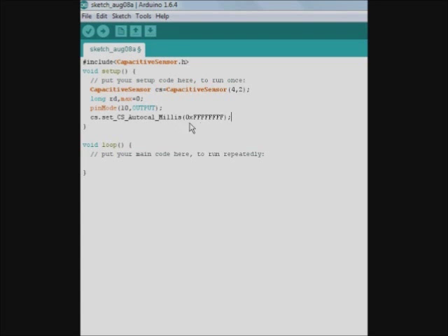What 0xFFFFFFFF does is it turns this recalibration off. So we'll just calibrate our Arduino once, and that calibration will carry on for the rest of our game, so that it doesn't create a problem for us. You can experiment with this and discover what it means if we change this or if we don't use this statement.